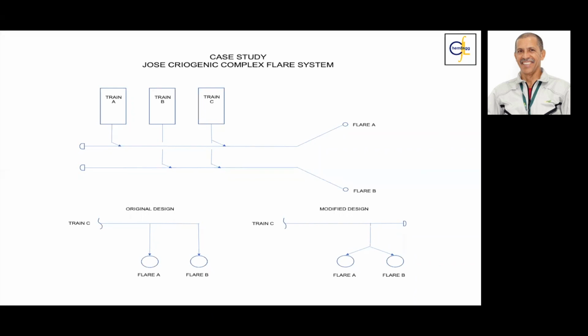However, during commissioning, prior to start of the plant, we test everything. When we tried to test the behavior of this connection, we introduced one potential venting similar to the flare capacity. And then what happened? When the system went into operation to test the venting, all the flow went to flare B. So all the flow goes that way.